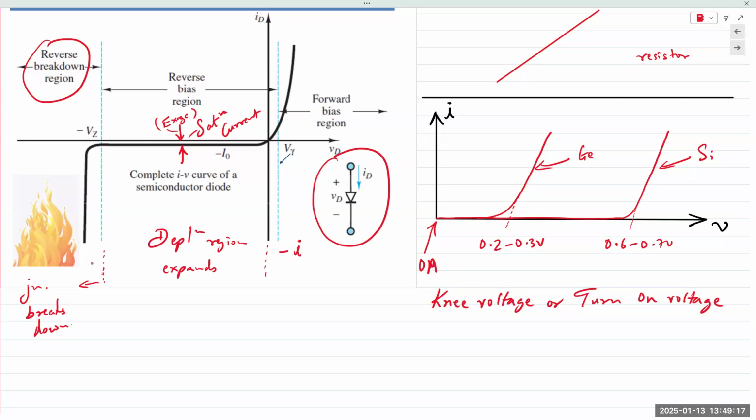Okay, so when somebody states diode voltage is 0.6 or diode voltage is -5, anode is always positive, cathode is always negative. So if you're measuring in the lab, you would take your meter, negative would be connected to the cathode, and positive connected to the anode. That's always your reference. Okay, so always keep that in mind.